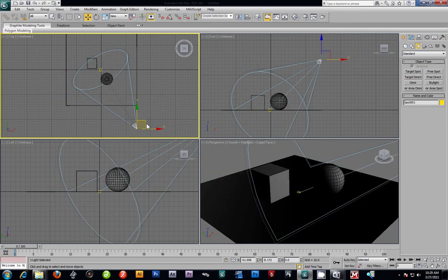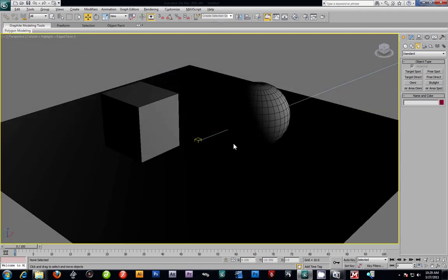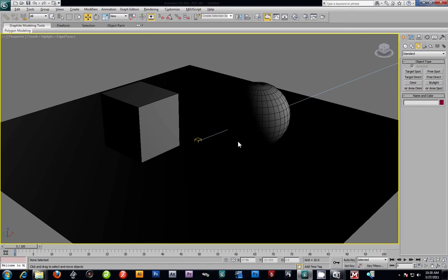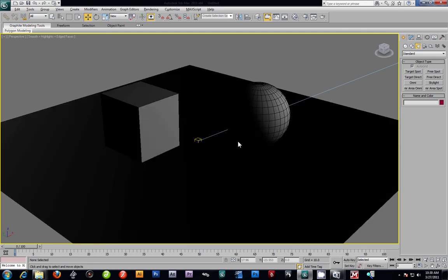All right, I'm gonna go to my perspective window, so I'm gonna hit Alt W. Now, if you hit Control L, that turns on your default lighting system again. Hit Control L again, so just do that a couple times. You can see you can turn on and off, and you're going to do that, especially when working lights. Sometimes you want to work on your geometry again and be able to see what's going on. So you might switch these on and off by hitting Control L.